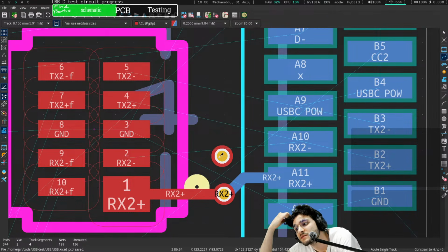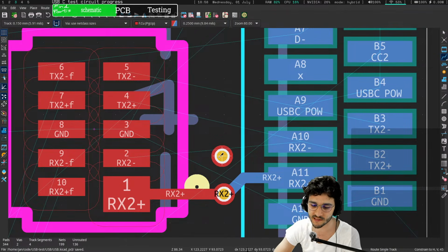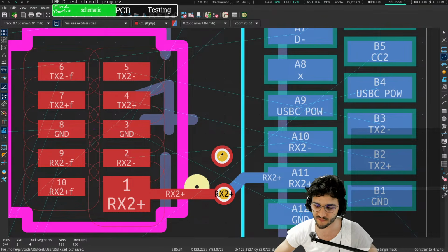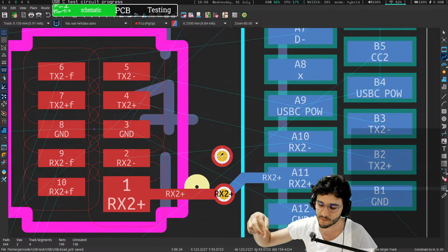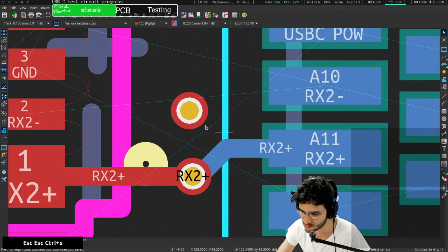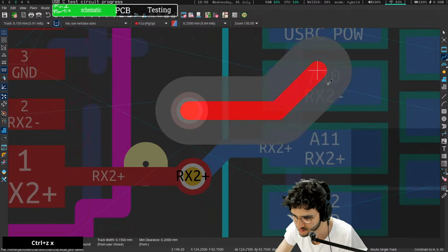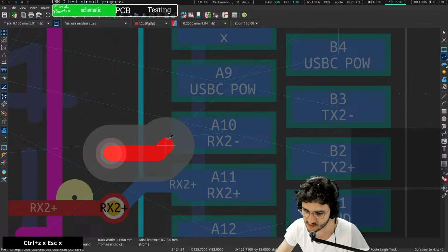It would be the most symmetric. Yes, it would be very nice, but it is also a little bit harder to manufacture because it's harder to solder something to the pad if there's a hole in it. So I'd like to avoid that, but also I'd like to understand how these vias even work.